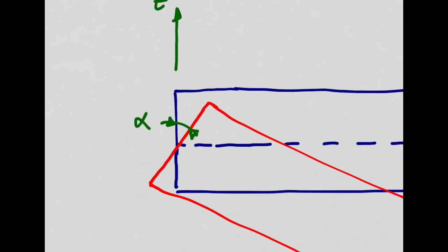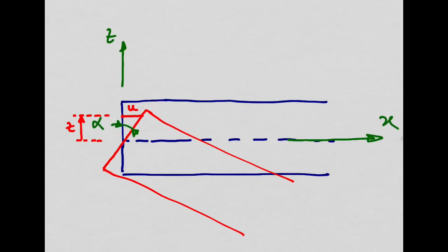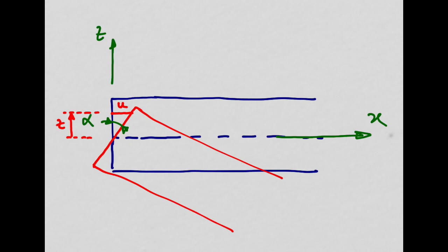So for example, if I look at this point, it will go from here to here, and this is my displacement in the x direction, u. So this point, starting from the neutral axis, is at a distance z from the neutral axis, okay? So don't forget, this is our coordinate system, x, z. So x is the horizontal direction, so the displacement along the horizontal direction is u, and this point along the thickness of the plate, which is the z direction, the transverse direction, is located at a coordinate z, that location z, okay?